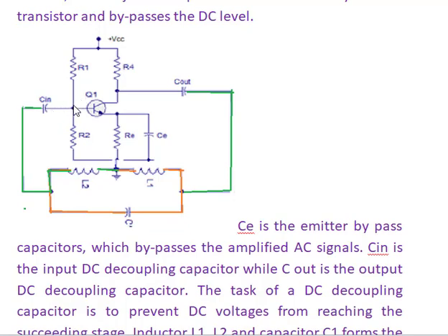This amplifier amplifies the amplitude by combining this AC signal with a DC part. Both the AC and DC parts combine here. Totally it is a DC voltage passing through the base of the transistor. This transistor amplifies and gives the output here. So the output consists of a DC level and an amplified output wave. Here the amplitude of the sine wave is constant. So this capacitor blocks the DC level and allows only the amplified constant amplitude output here.